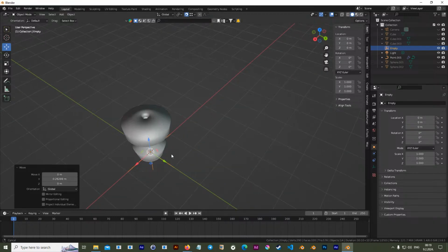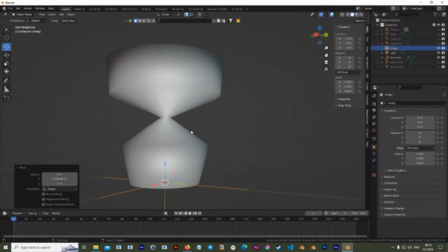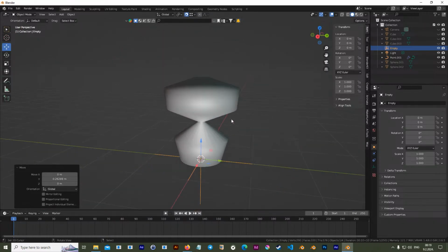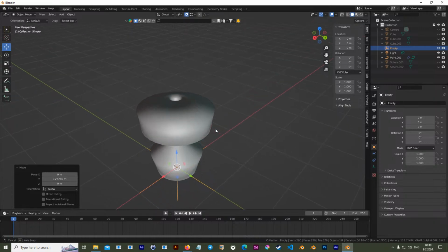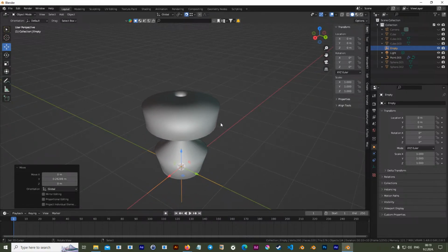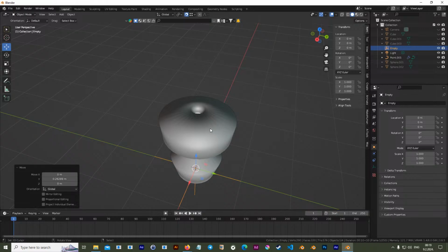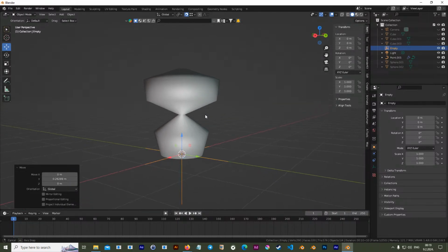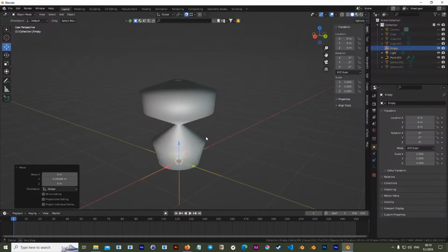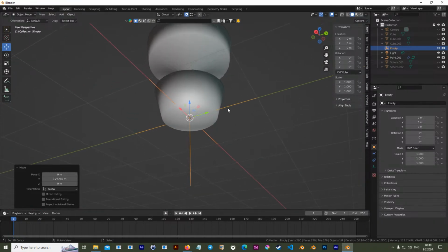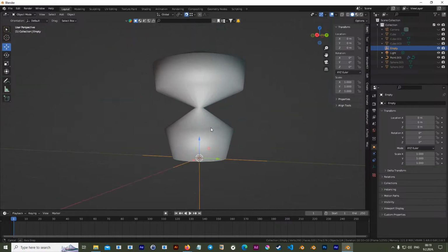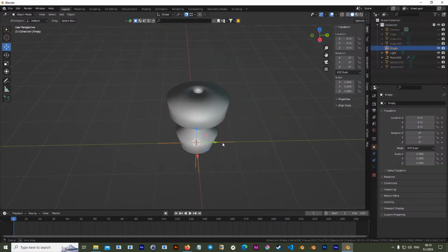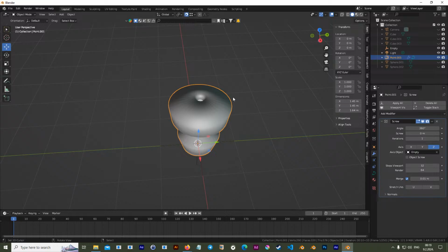But if you want to model a glass, a bottle, or cup, anything, as I said, table leg, anything that's symmetrical around, you can use screw, and with your axis 3D helper right in the middle of your object.